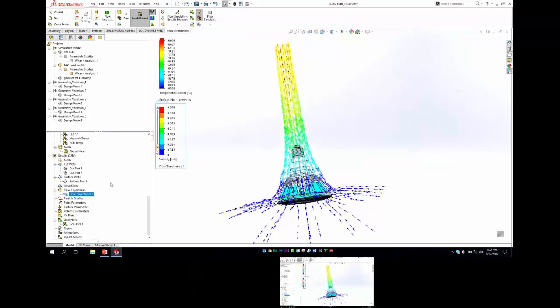Okay. So back to our question. Did this answer the optimum number of heatsink fins? Didn't really answer that. This told us kind of how does 20 fins look? If you have 20 fins, this is what the temperature environment is. But we'd have to copy this and do a bunch of geometry changes and test a whole bunch of them to understand what changing those fins does.